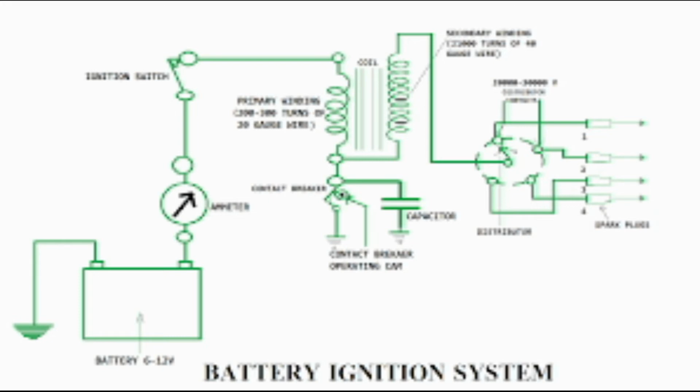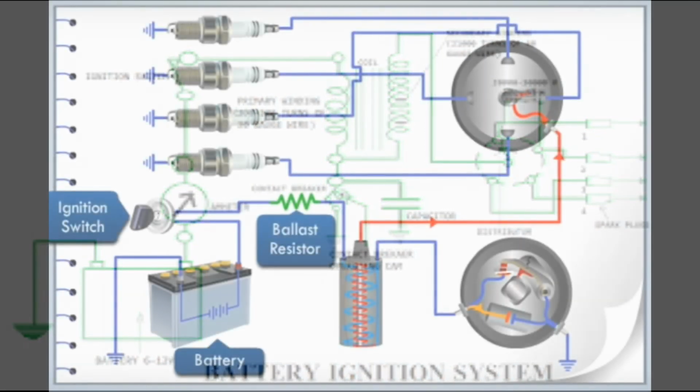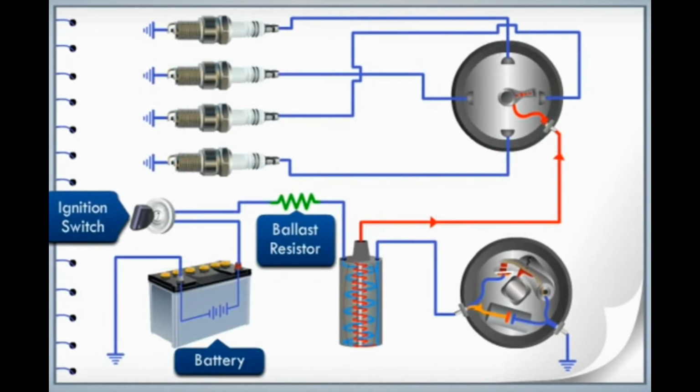It also contains some other auxiliary units too. In the lower part of the housing, it has a speed-sensitive device or governor whose main function is to advance the spark with the increase in the engine speed. Contact breaker assembly is present above this, which can be rotated to adjust the timing of the spark. In the upper part of the housing, a high-tension distributor is located. It also carries the vacuum ignition governor which serves to retard the spark as the load on the engine increases.